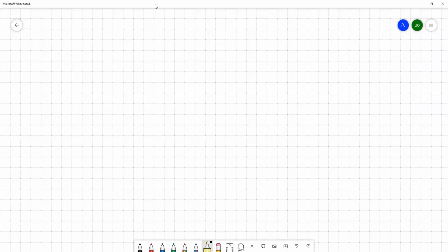So the next is, if you want to make this transistor active, we need to satisfy these two conditions. One is you have to make the base emitter junction forward bias, and the other is the base collector junction reverse bias. So if you want to make your transistor an active device, we need to maintain these two conditions: the base emitter junction should be forward bias and the base collector junction should be reverse bias. So how do you maintain this?